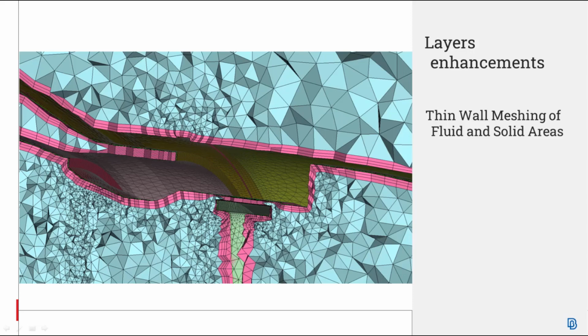It automatically identifies regions in proximity and fills them with layers, providing a result similar to, for example, the mapped mesh. This is ideal for meshing thin regions or sheet metal parts, for example for conjugate heat transfer applications.